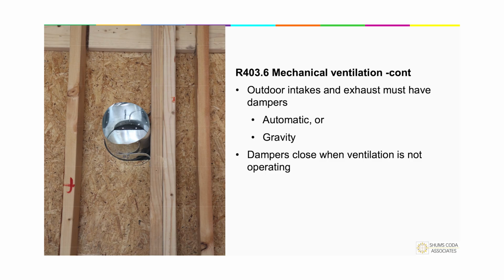So remember, anytime you have an inlet or an exhaust outlet, it is required to have a damper. It has to have the damper close when we have ventilation not operating.